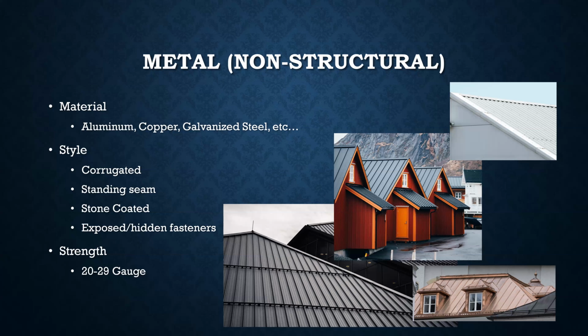And then there's standing seam roofs, which is like that cabin photo in the middle there with the red walls. Standing seam panels are usually rolled out on site, cut on site, and formed on site to fit the roof as it's made, unless they're prefab, which can be done. But that is what they look like. Frequently, the fasteners are hidden. When you install one panel, the fasteners go next to the panel, and then the next panel covers them up. So you end up not seeing any fasteners. It looks very sleek and modern, looks really nice. So that's another look, the standing seam.